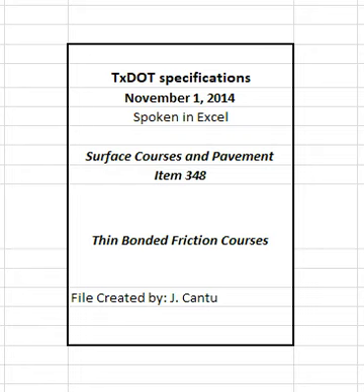4.4.2.2.6 Full approval of JMF1. The engineer will grant full approval of JMF1 and authorize the contractor to proceed with developing JMF2 if the engineer's results for the trial batch meet the requirements in Table 9. The engineer will notify the contractor that an additional trial batch is required if the trial batch does not meet these requirements.